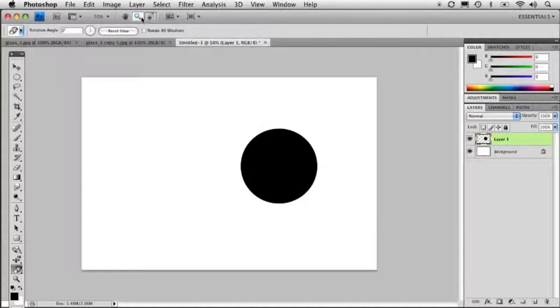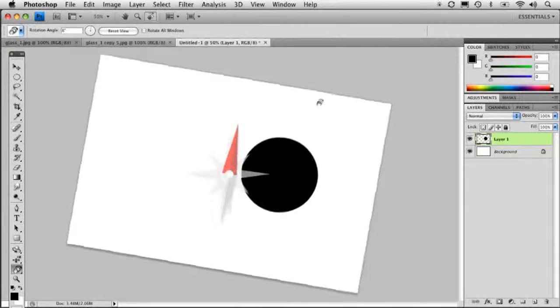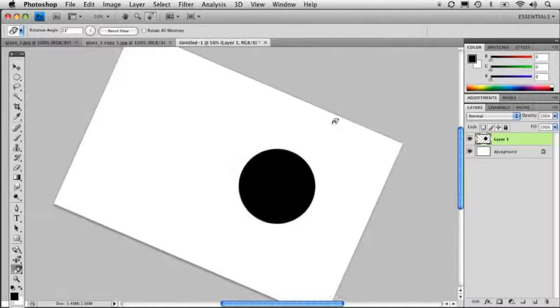And if you're an artist, or perhaps you're working on a Cintiq or some kind of display where it's not really easy to turn the whole device, and you don't necessarily want to rotate your document, you can rotate the canvas. Now, what I mean by rotating the document is completely taking it and redrawing the pixels by rotating it 90 degrees clockwise or counterclockwise or such. With the canvas rotation tool, you're simply repositioning it as if you were setting a piece of paper on a table and you slightly turned it at an angle so you could write or draw at a certain angle, something like that.